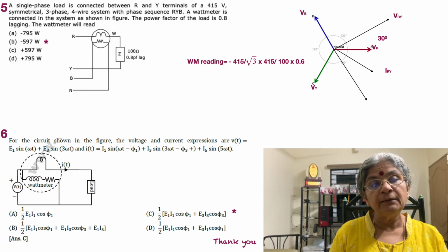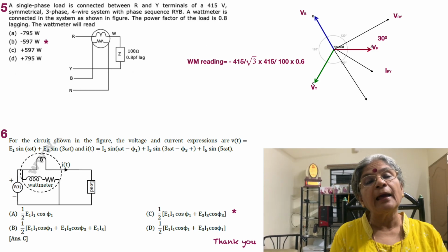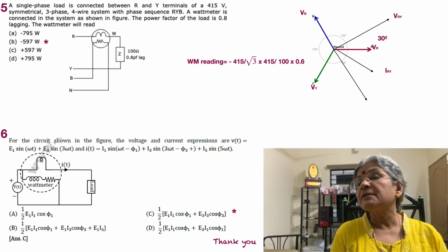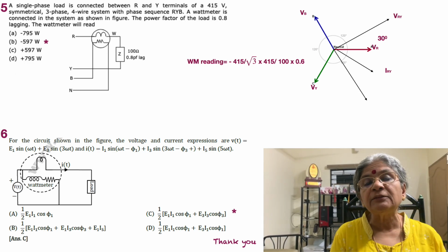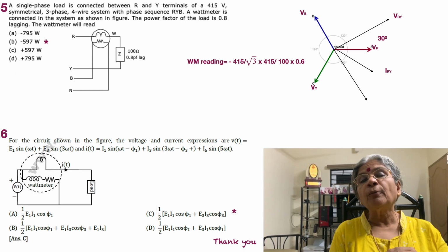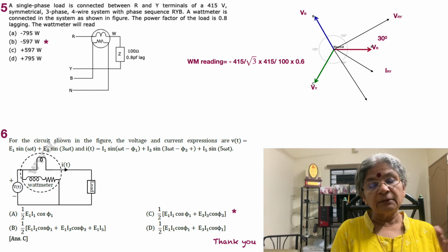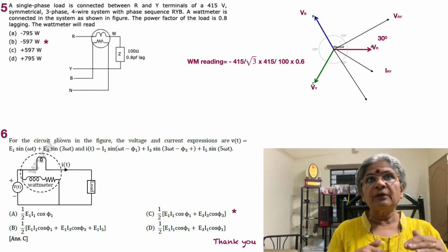So between the current and the voltage, we now have an angle given by 90 minus 36.9 or something like that, and its cosine value is now not 0.8 but 0.6, the other quantity. If the angle is 53, then you have a power factor of 0.6. If the angle is 36.9, but 90 minus that, then it's going to be 0.8.